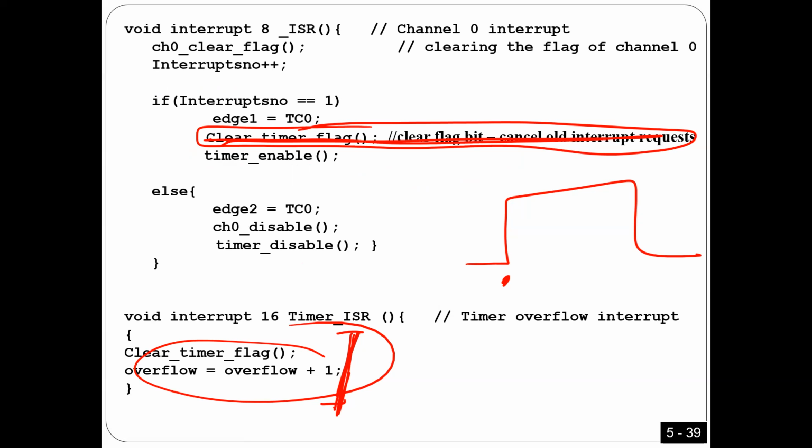What happened is, because the TA made this mistake, or even myself, I made this mistake in the beginning. I was expecting to get 2 overflows. I found that I get 3. I was expecting to get 3 overflows. I found that I'm going to measure 4. I was expecting to get 5. I'm going to get 6. So I noticed if you don't write this one, always I'm going to get 1 overflow more than what I'm expecting. Why? I should start counting overflow from here because I enable it here. Okay, I'm going to tell you why.